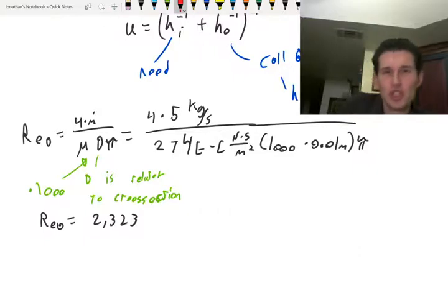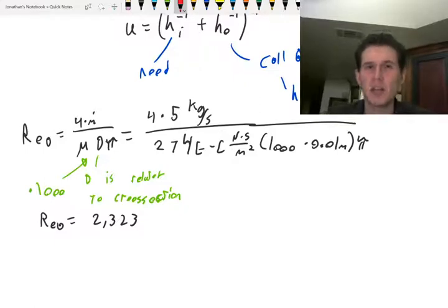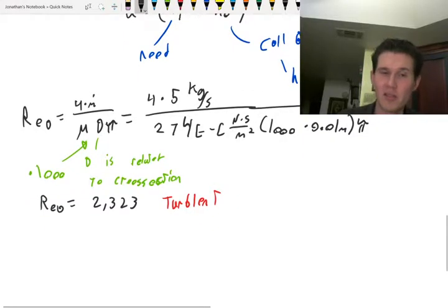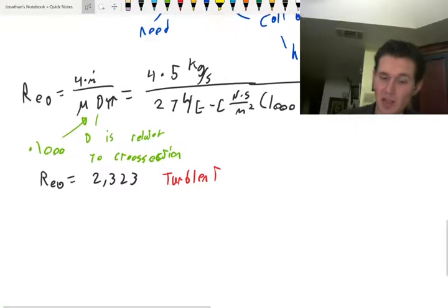So you've got boom, shh. And what that does is it creates some vibrations in the machine. What this means to us is that it's going to shake that fluid up. We can get laminar to go above 2,300, but only under really nice conditions where everything's stable, nothing's changing. So we're definitely in the turbulent region. We say we're in turbulent because it's over 2,300, but we know we're in turbulent because it's a real machine, it's not stable. And then you have a whole pipe network coming into it that probably enhanced the actual turbulence to begin with. So it's turbulent.